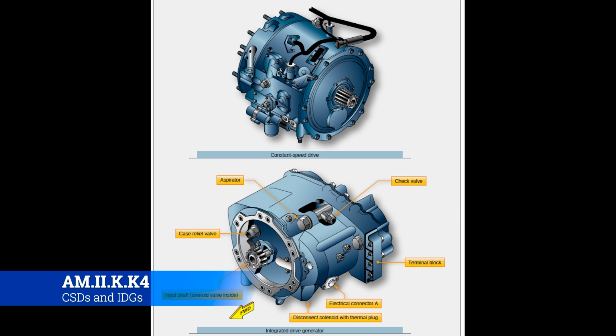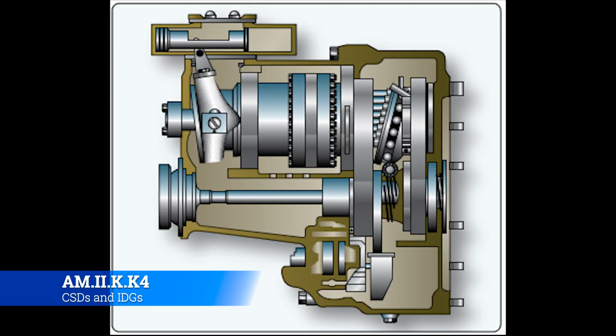Now, the CSD is a hydraulic unit similar to an automatic transmission found in a modern automobile. The engine of the automobile can change RPM while the speed of the car remains constant. This is the same process that occurs for an aircraft AC alternator. If the aircraft engine changes speed, the alternator remains constant. A typical hydraulic type drive can accomplish this just in the same way that a propeller governor keeps the propeller RPM the same speed, or the car keeps its speed constant despite lower power input.